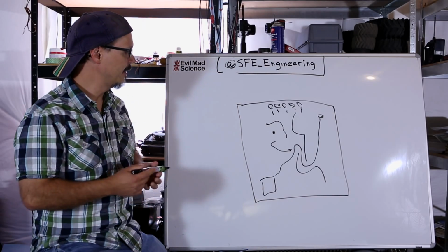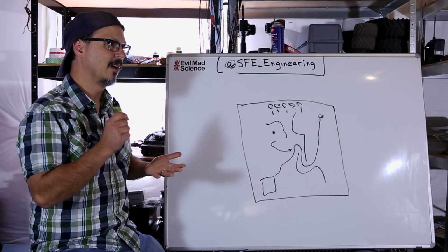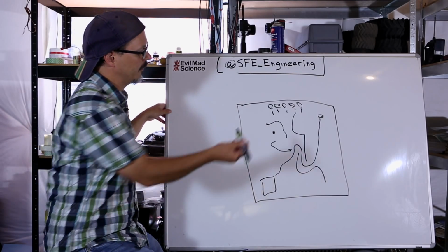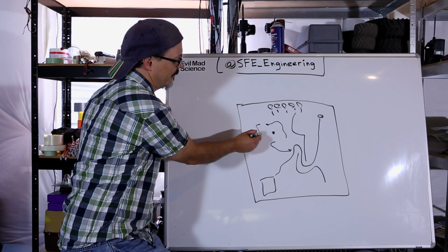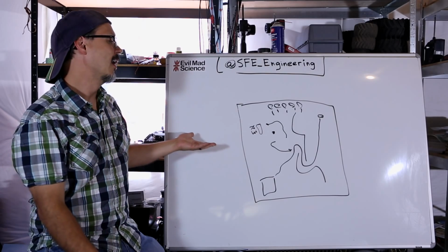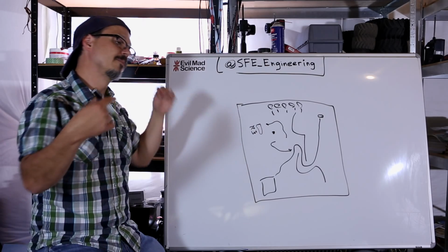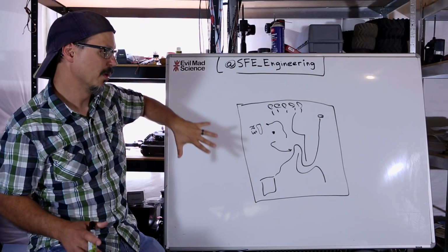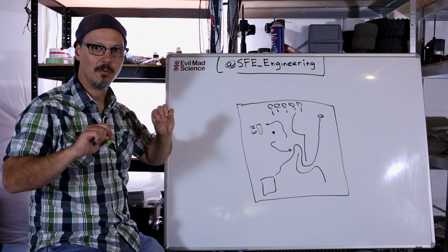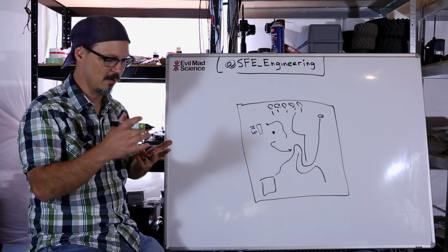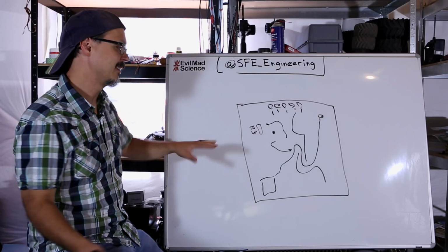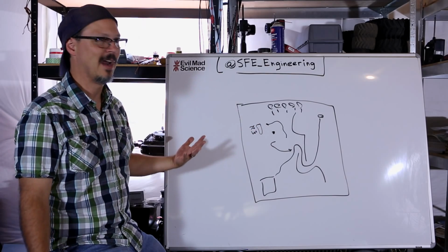A lot of times, the CAD program like Eagle will, by default, put component labels. Like if I've got a resistor here, it's going to say that's R3, and it's going to put it in the silk automatically. At SparkFun, we don't really do that because we want the boards to look really nice, but if this is a board that I am actively working on and I need to get in there with probes or an iron to rework or what have you, I'm going to want those. So think about what your silk is going to be, and how it's going to help.